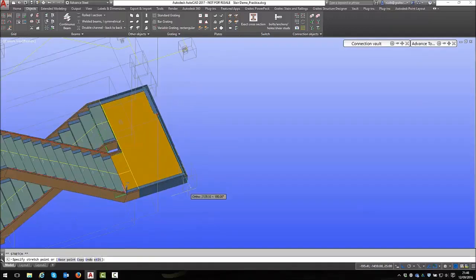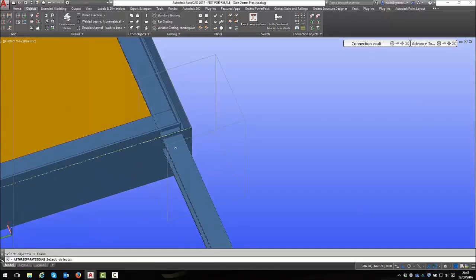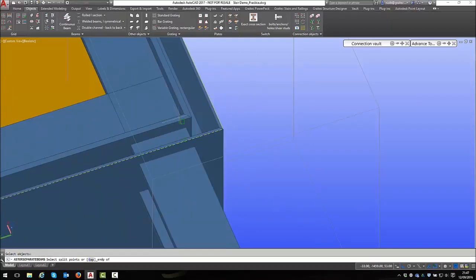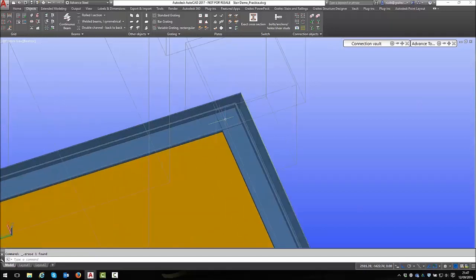I'm going to drag this by. I'm going to split the beam. No measuring involved, look. I just know where it has to go. There it is. We're going to delete that. Here's my compound beam. I need to weld that on. So I'm going to weld here to here, and I might go to midpoint somewhere in there.